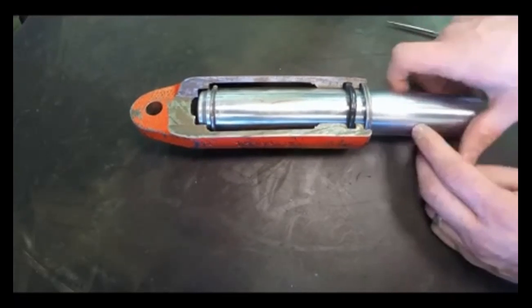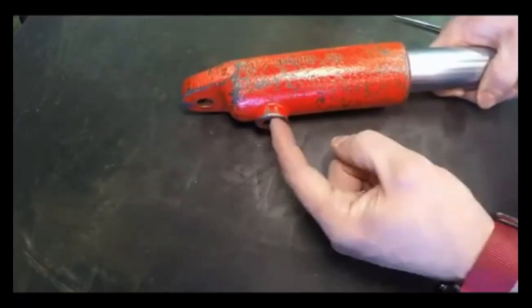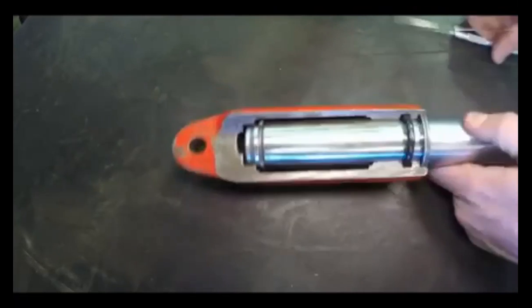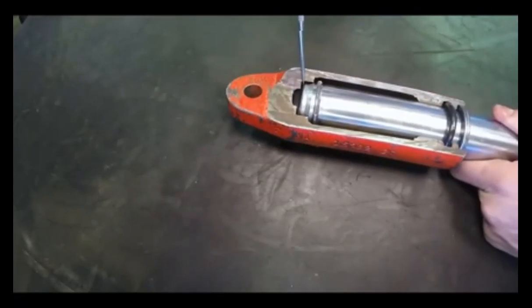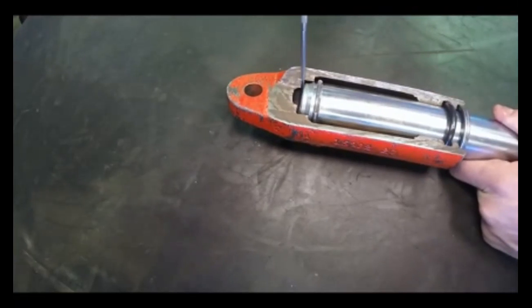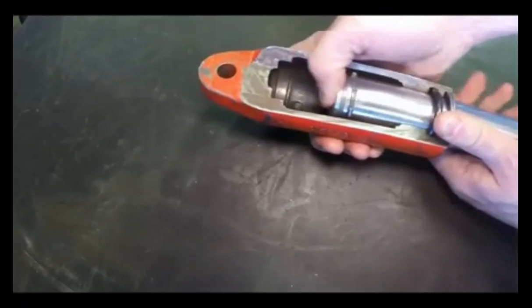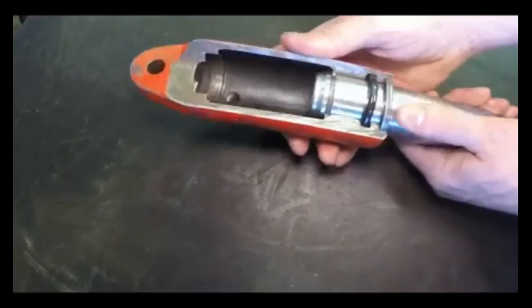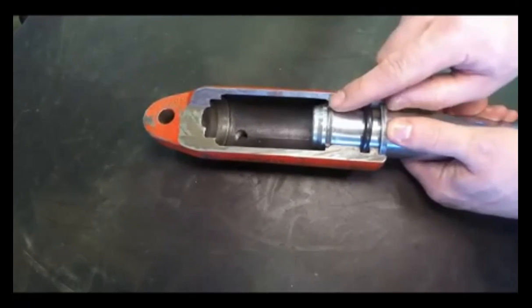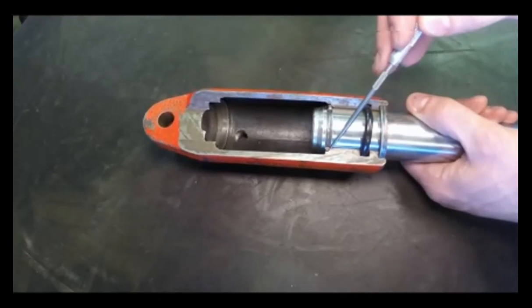The simple operation of this cylinder is that we send hydraulic oil into its work port. It creates enough force by pressure being built underneath the surface area of the rod, and the entire rod acts as the piston and is able to travel until the O-ring bumps against the housing.